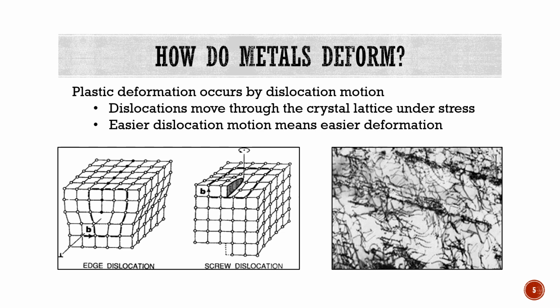As deformation continues, dislocations multiply and interact with each other. They can form complex, tangled networks inside the material, similar to a dense web of intertwined lines. This growing dislocation structure allows metals to deform plastically, making them tougher and more capable of absorbing energy without fracturing.